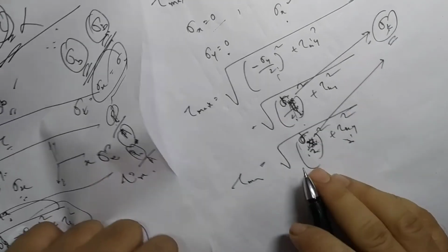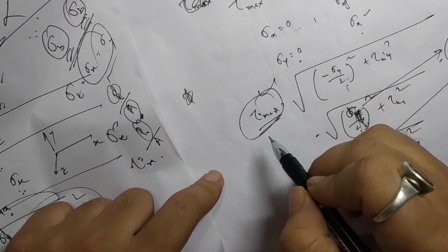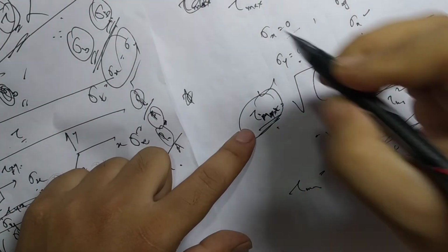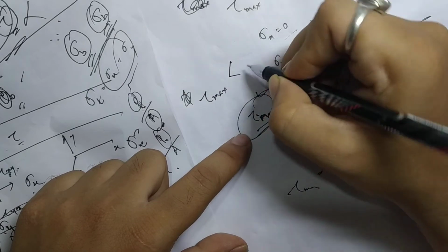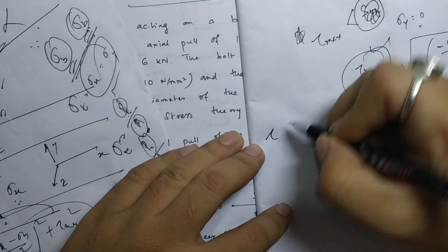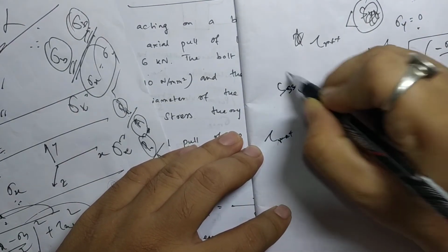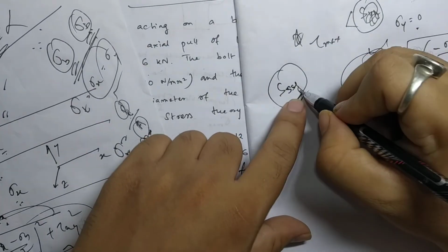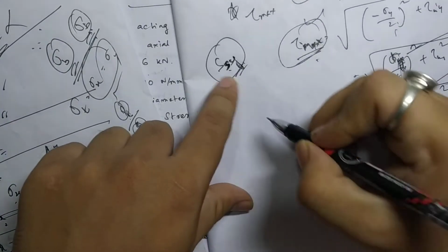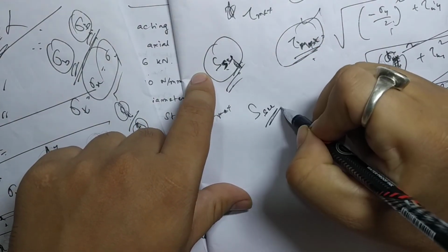Okay, then tau max is your maximum allowable stress, or the stress which you can allow according to your design, which should be less than your failure stress. SY, not SYT. For shear we learned that SSY, the yield in shear, is your failure criteria, and if ultimate is there, then SSU will be the failure criteria.